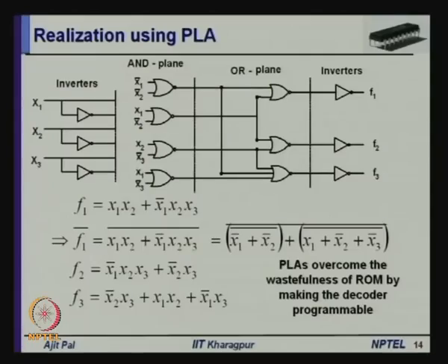So, that is the basic philosophy behind the programmable logic array, and there are several structures. The most common one is this AND OR realization. Since you will require both complemented and uncomplemented outputs, each input is complemented and those outputs are fed to a stage known as AND plane, as if you are doing AND OR realization. So, you are realizing this in this form, say x1, x2, x1 bar, x2, x1. This is realizing the AND operation and this will perform the OR operation.